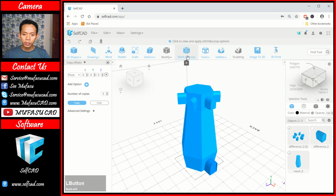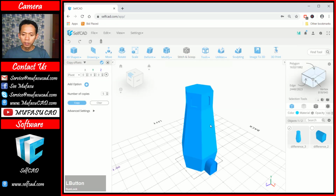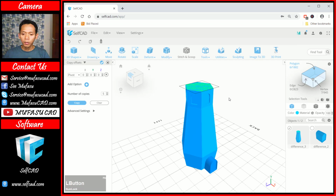Next, we can use a different command. Okay, we subtract with this difference, and you can click in here to subtract. You can click OK to apply. Okay. Now we can select this object, and you can use polygon again. I will select this face.